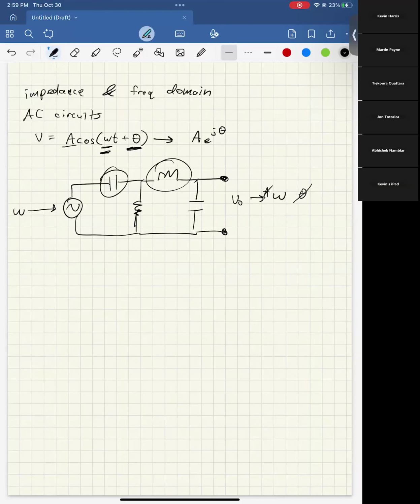because what we do is we take our capacitors and we take our inductors and we say, okay, we're going to say Z, this is the symbol for impedance. It's like resistance, but in complex numbers. So the Z of a capacitor is 1 over, oh, and j is just the square root of -1. Since i is already used by current in electrical engineering, we use j instead. So don't get confused about that.